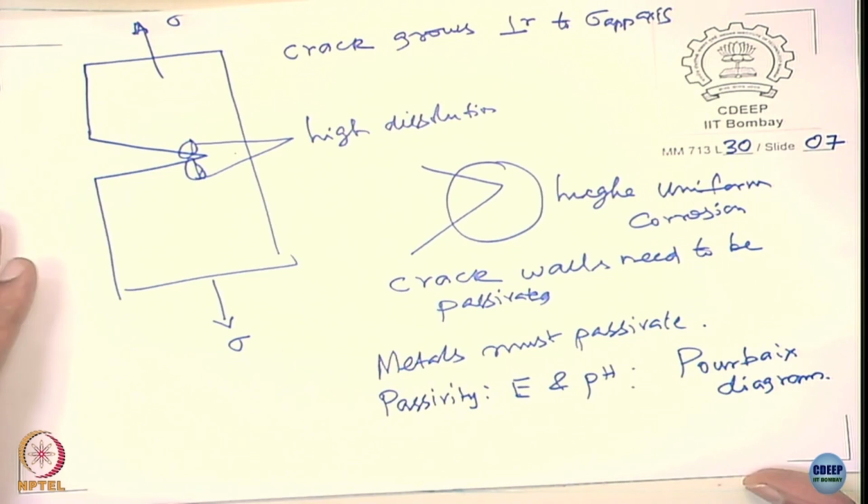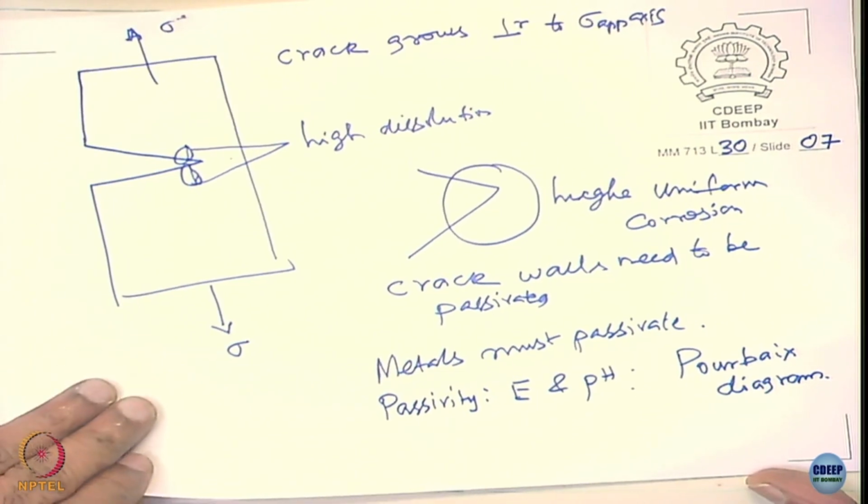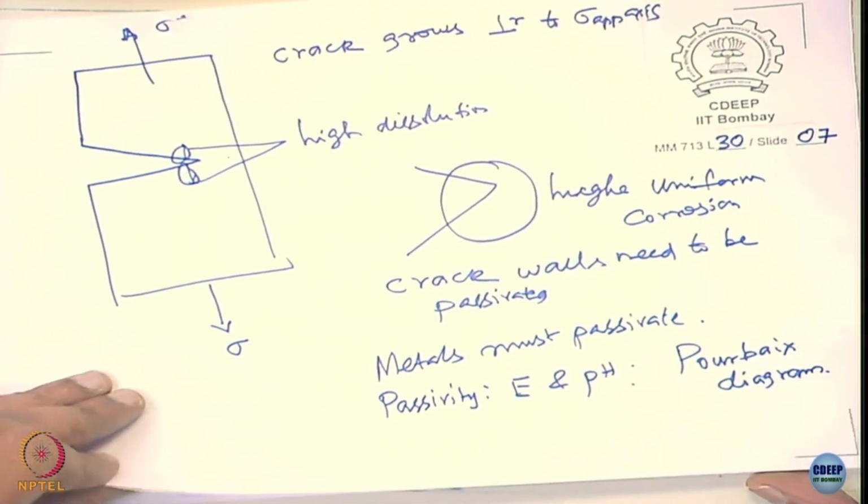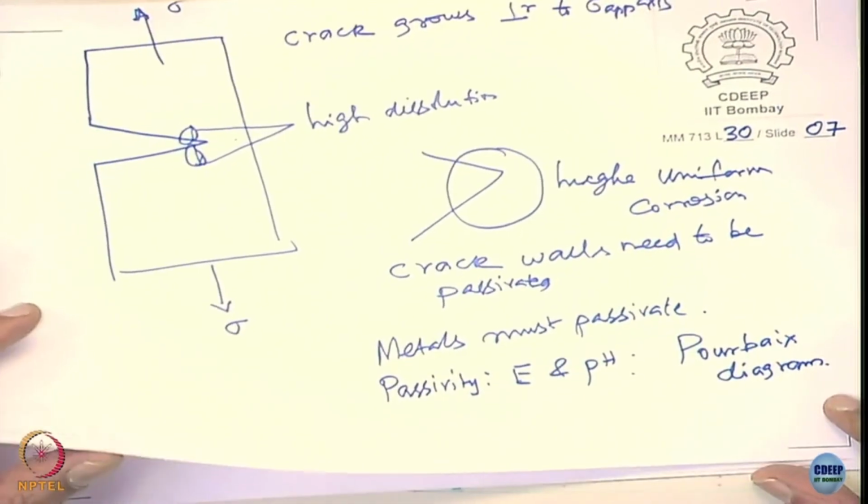So when we said nitrates, carbonates and phosphates, they are the ones that passivate the carbon steel, and they also promote stress corrosion cracking. If there are no applied stresses, they will be very happy, the corrosion rate may be very small. Because there are tensile stresses, stress corrosion cracking occurs, am I right? So passivity is a very important one.